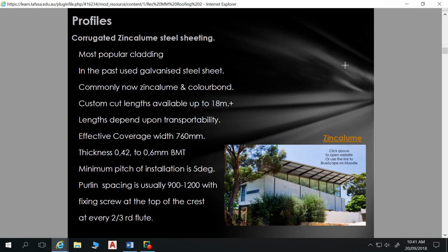Both of these are galvanised iron, and both have that large fleck in it. One's the traditional profile, which is very high, it's 21mm, and it's a rounder radius. This one is 16 millimetres from flute, so from crest to valley, and not as round. So we've got all of our many different profiles. We did this last week.